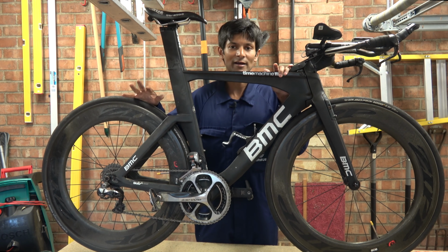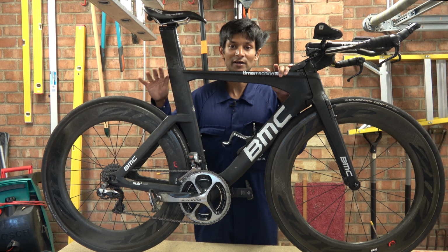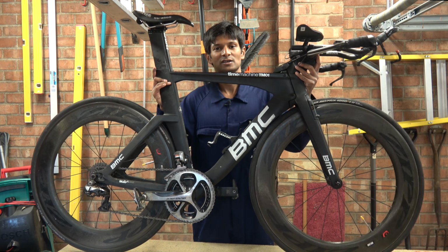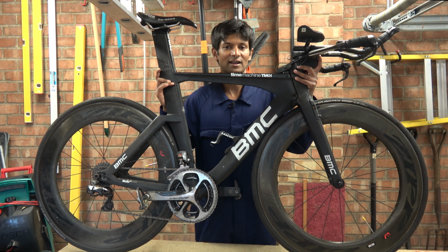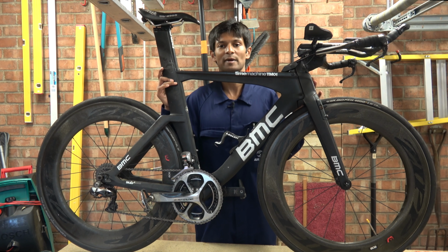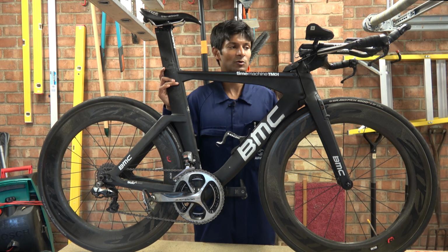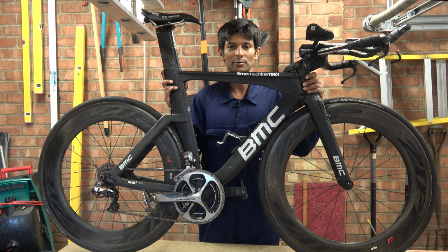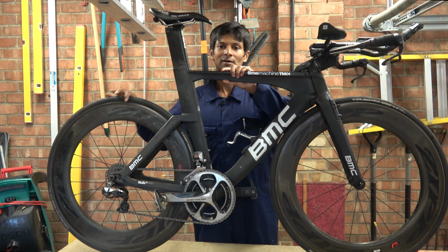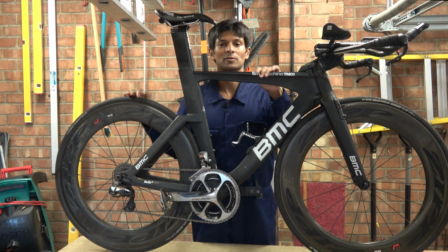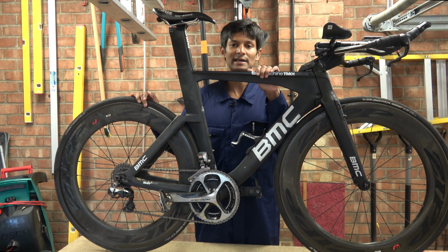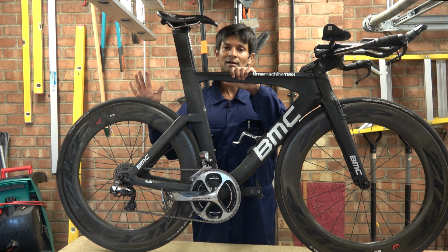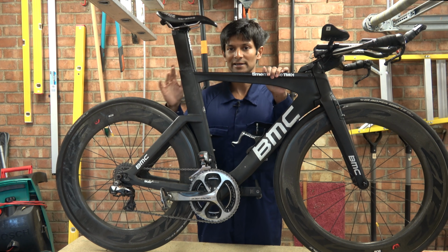If I just talk around some of the areas where you get axial loads first, the most predominant one is the headset. So this is the best example of an axial bearing on the bike. So headset bearings are predominantly biased towards axial loading, but they also have an element of radial loading. Radial loading is turning, so that is the wheel is taking a radial load by spinning, but if you are cornering and you apply a sideways load, that is an axial load on the bearings.